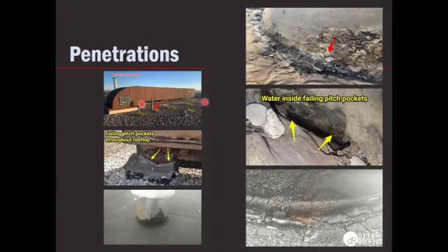Pitch pockets or gum pans are another type of roof flashing that can go around a penetration. This is also a maintenance item, and you need to be renewing the sealant on a regular basis. Otherwise it gets to this point where it's all failing and water is getting in. This was actually happening throughout the entire roof, not just in the one unit where the leak was occurring.